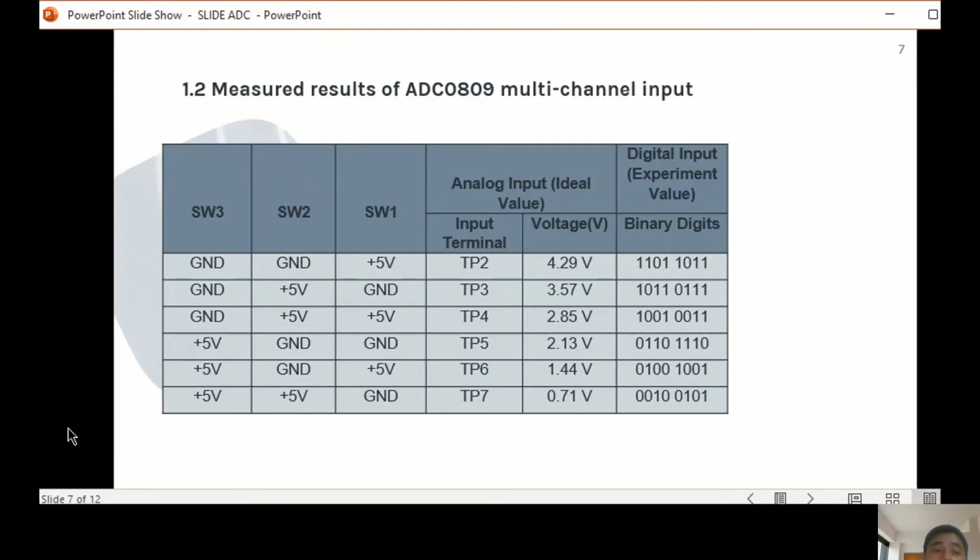There are two factors that determine the accuracy of the digital value that captures the original analog signal. These are quantization level or bit rate, and sampling rate. Bit rate or quantization gives the smaller output changes in the analog signal value that result from a change in the digital representation.